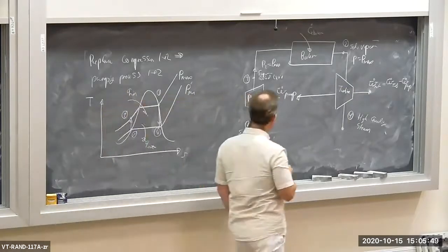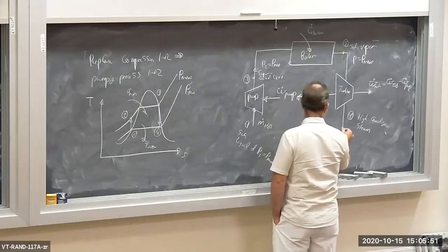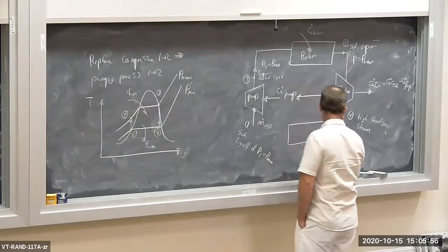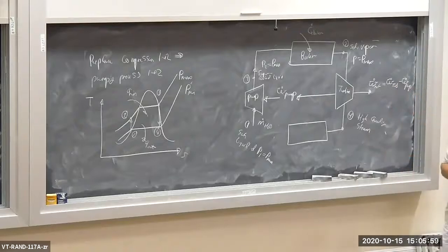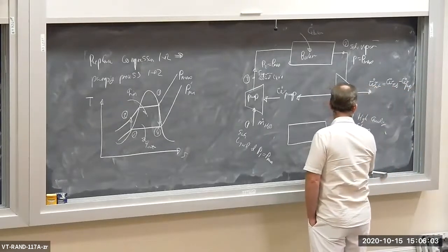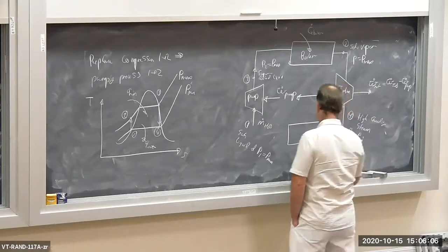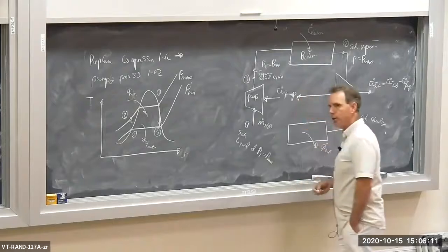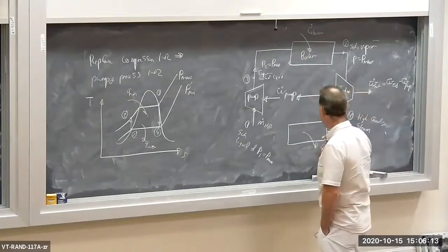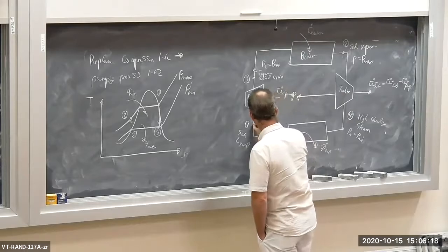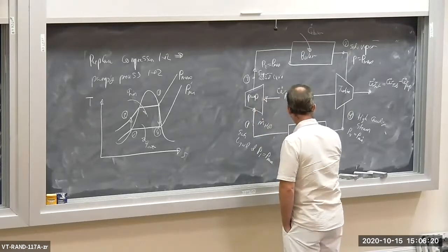Okay, now we got to get rid of the excess heat to complete the cycle. We pass the saturated mixture, high quality steam, at low pressure. By the way, P4 is back down to P min. And we reject the heat, Q dot out, and the Q dot out occurs in a condenser. We take a vapor and we condense it to a saturated liquid. So this is called a condenser.